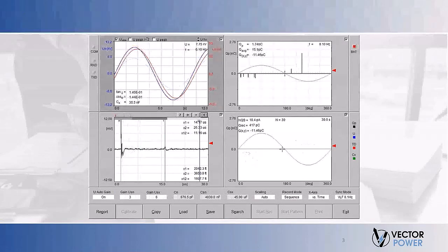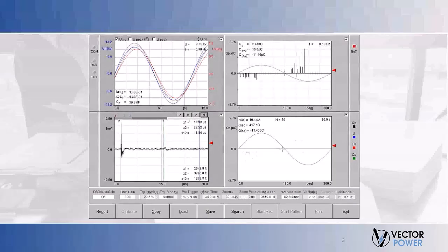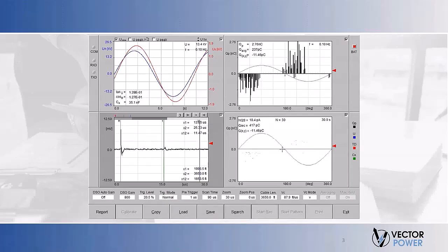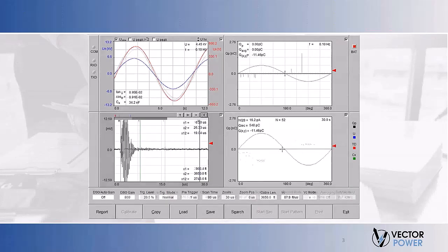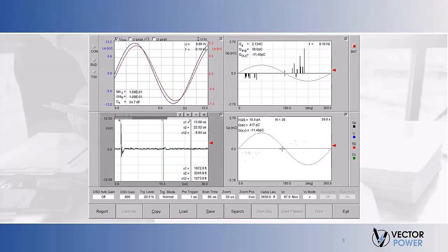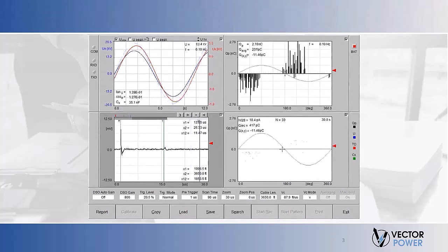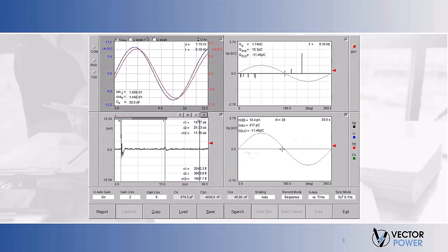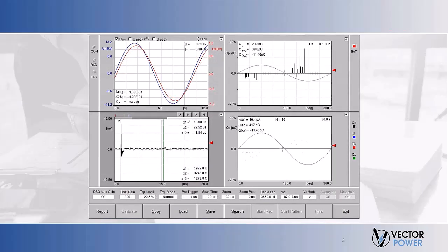This is particularly true in environments with high background noise levels that operate within the same frequency band as the PD signals. As a result, there has been a growing trend in conducting PD measurements on cable systems in the field, especially on medium voltage systems.